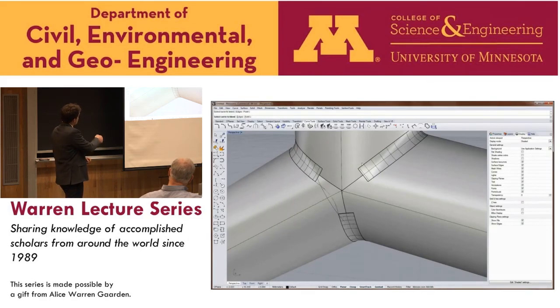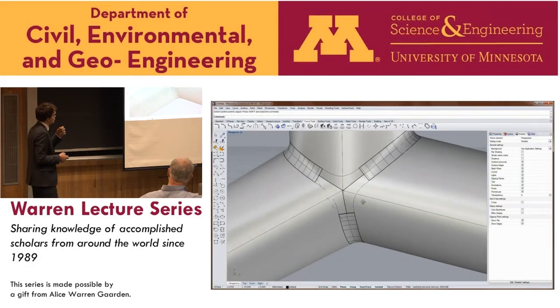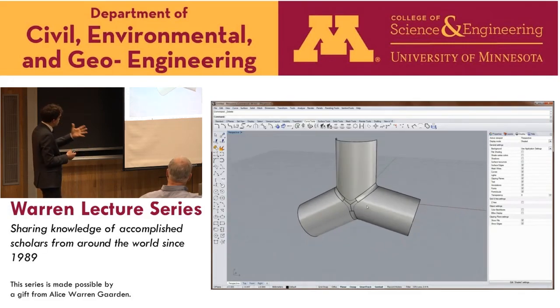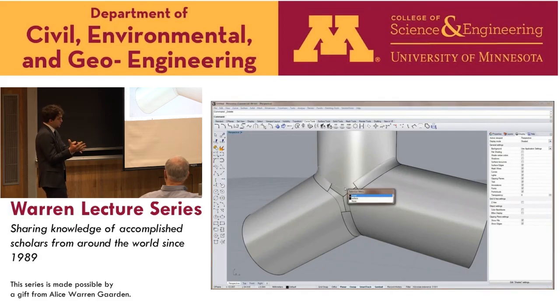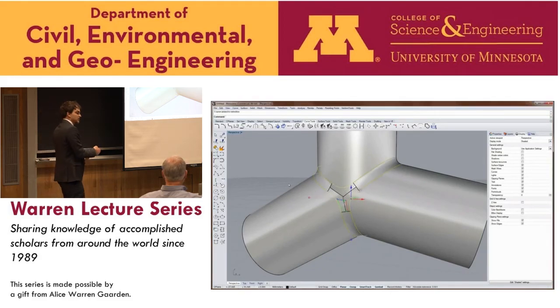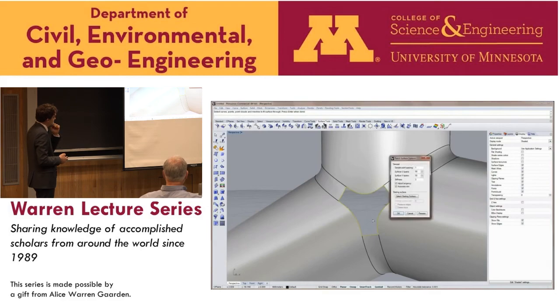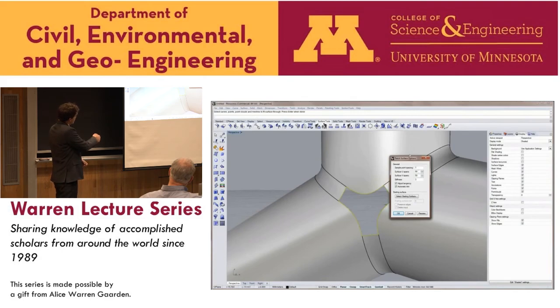The trimming concept does not change the original parameterization of these tubes, but in a first step, he adds so-called trimming curves. These are these guys here. These are spatial curves that are defined in the physical space as well as in the parametric space of these surfaces, and they have topological properties associated with them, such that you can trim away parts of existing surfaces. So that is this trimming procedure. At the same time, you can also add additional surfaces, and that's what he's doing now, that try to fit as best to these trimming surfaces as possible, to any given tolerance.